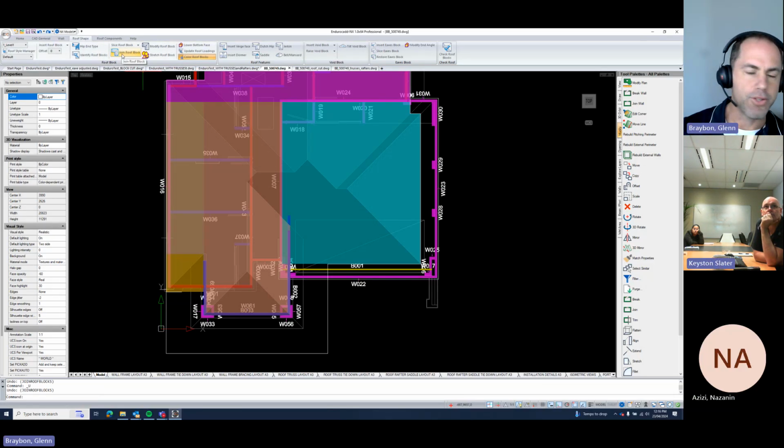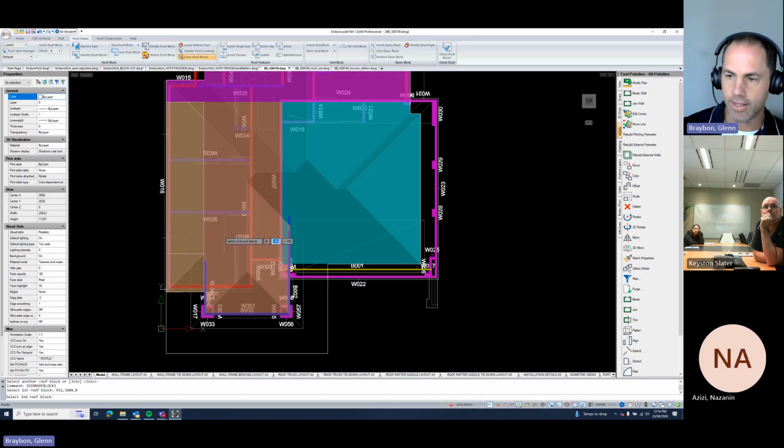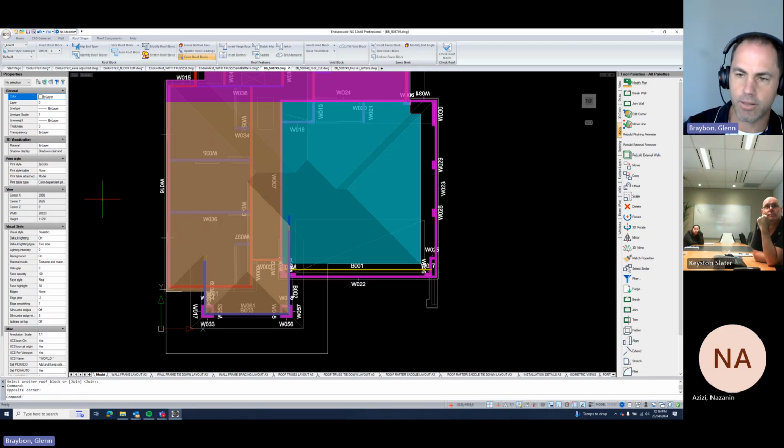So just to go back over that, I obviously Control Z and I'm back to those 3 roof blocks. So if we hit join roof block, left click, right click, and then join roof block, left click, right click. Recent commands are obviously at the top, or I think spacebar does the same thing. So spacebar will give you the last command.